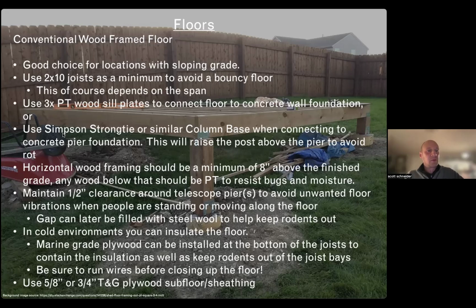So wood flooring is a great choice for locations where you're sloping, where you're doing a conventional wood frame floor with 2 by joists. I think 2 by 10s is a good starting point. The sizing really depends on your span.